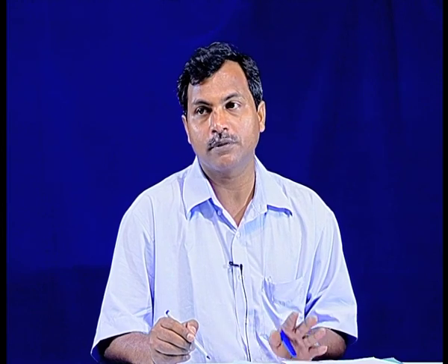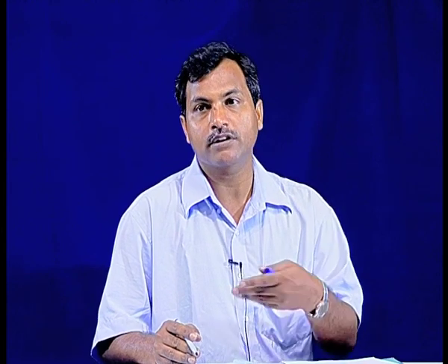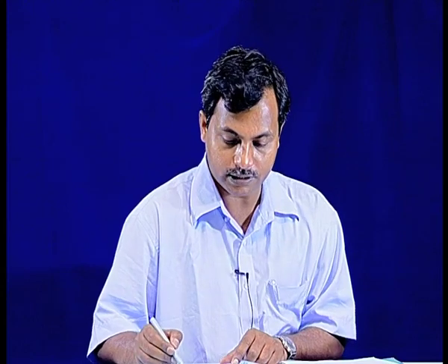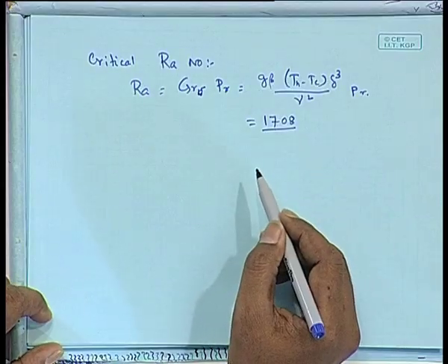It is known as Orr-Sommerfeld analysis, which we have not done, but it is material of any advanced fluid mechanics course. It is also called normal mode analysis. In the same way, you can estimate the transition from laminar to turbulent flow and find the critical Reynolds number. In a similar way, you can find the critical Rayleigh number here, where there will be occurrence of natural convection.